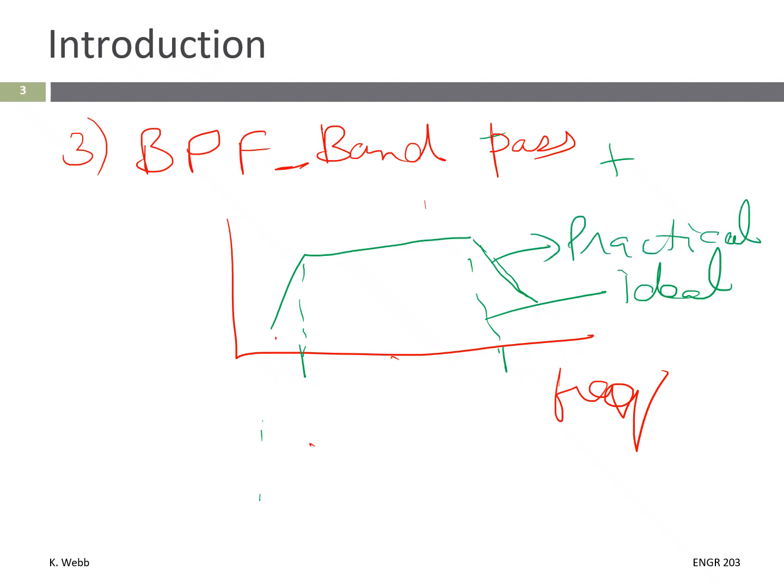When the maximum bandwidth is reduced to 3 decibel, the meeting points of the 3 decibel level on the frequency response curve are at two different frequencies. One is the upper cutoff frequency, the other one is the lower cutoff frequency.